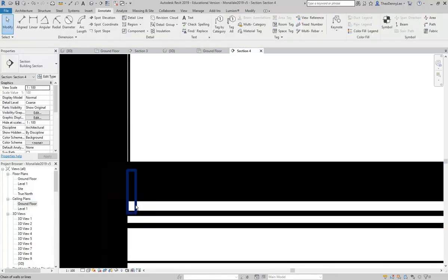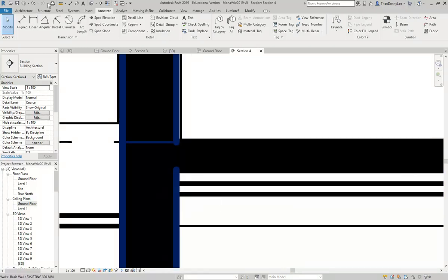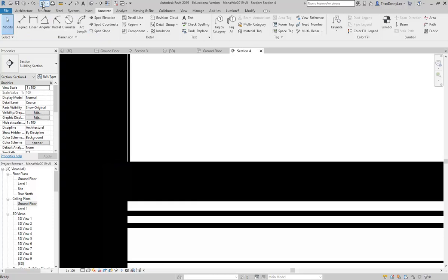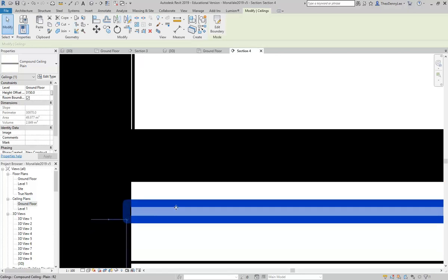Right, so again, for interior design especially, you don't always need to show all of the structure, but you need to allow for it. So in this case, I've worked out I need a bit of thickness there, but I don't need it to be as much as it was. So again, just to go back, I've just brought the ceiling up, and I'll show you the height that I've ended up with. It's now 3170. That's not a good number, so I'll just change that to 3150, maybe, just a round number.